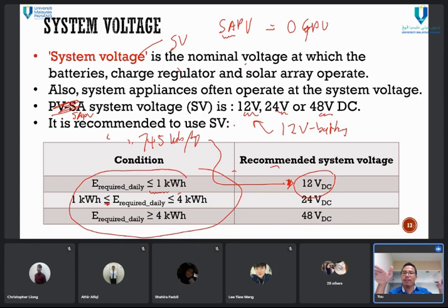Originally, if you have a 12 volt battery and live like that for several days, it will maintain between 12.2 and 12.4 volt, around that nominal voltage. Then after you use it, it will drop. If you use it longer it will drop gradually, and if there is too much energy spike current, it will drop suddenly, quickly reaching the bottom value of 10.8.